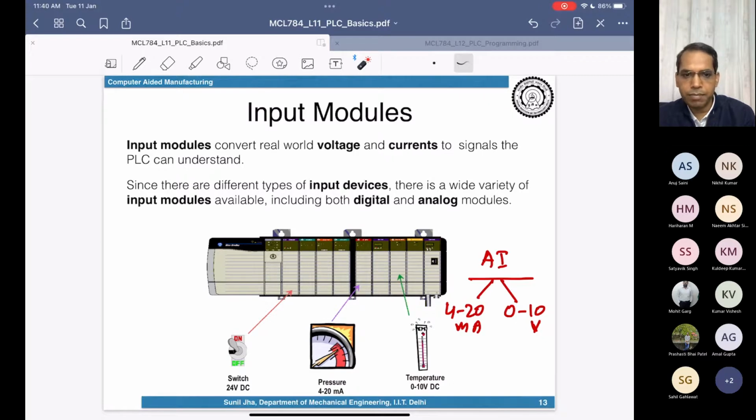So this gives me the same current at the controller level, irrespective of the length of the wire, because depending on the external resistance, the sensor will apply the voltage needed to keep the same current flowing, whether it's a 1 meter, 3 meter or 5 meter length, irrespective of the wire length and the drop in these wires. My sensor will be able to maintain the constant current in the line. That way, if I place the pressure sensor at a 10-meter distance, it is not going to make any difference to the controller's understanding of how much the pressure is at the site.